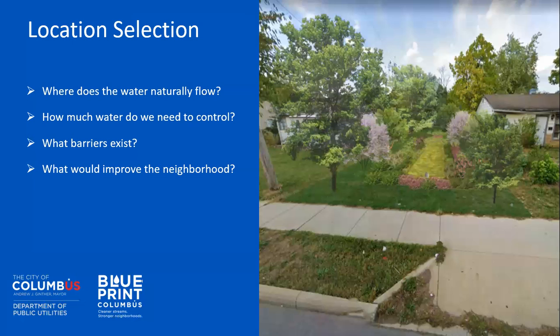Going down the order of hierarchy, we would next do some of the rain gardens behind the curb line. We call them right-of-way rain gardens. And the next one is the bump outs, as they're called. They're the ones that you may see along Joyce Avenue, where they sort of jut out into the pavement. Those are less desirable because they can capture less water. They also take away parking, and they have some traffic calming effects as well. And then lastly, permeable pavements are another tool in the toolbox, but they're really expensive. So they get used kind of infrequently.